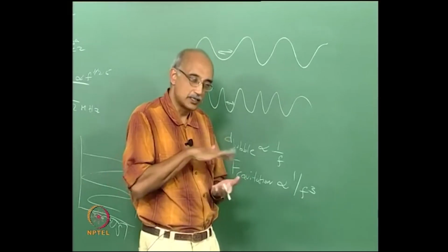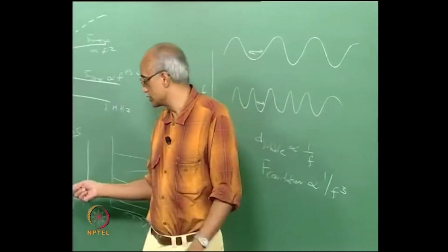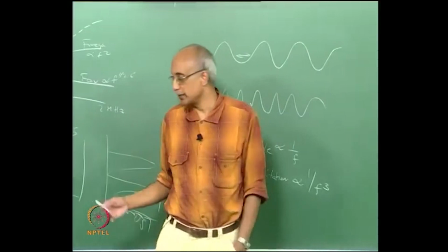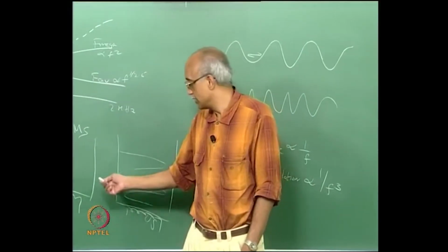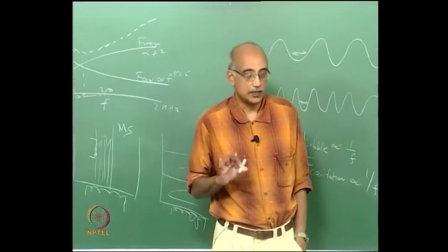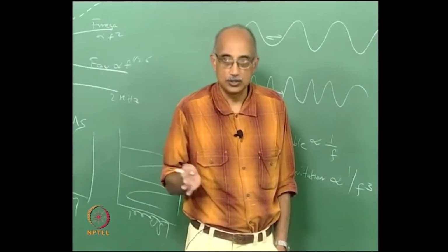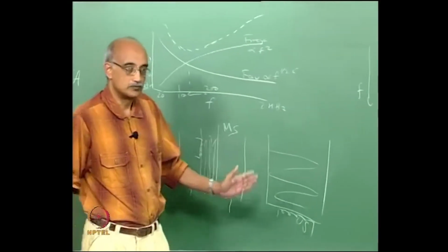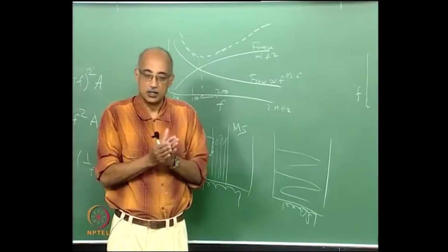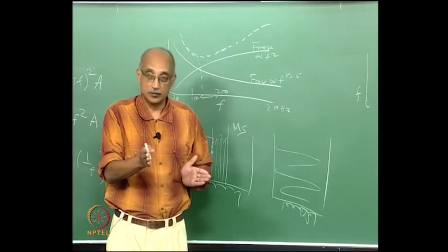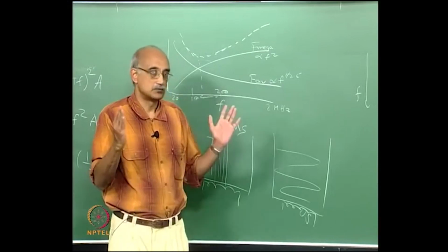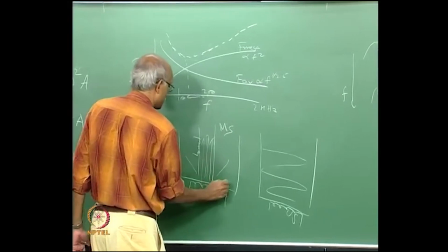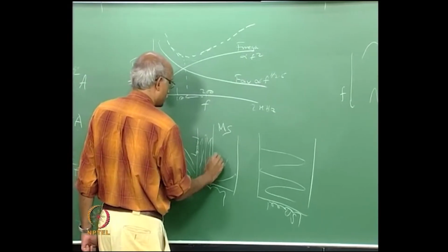important. Of course, there are still some biases. If you get very close to the transducer, even in an ultrasonic tank, you will measure slightly higher intensities compared to when you are farther away. And similarly, there are wall effects, but those are fairly subtle effects. They are not order of magnitude effects, whereas in the case of a megasonic tank, you virtually fall off the cliff. If you are in the plane, you get high energy. As soon as you move even slightly away, in conventional megasonics, the energy level drops almost to 0. So, by sweeping, we are now trying to broaden this plane and make it more uniform.